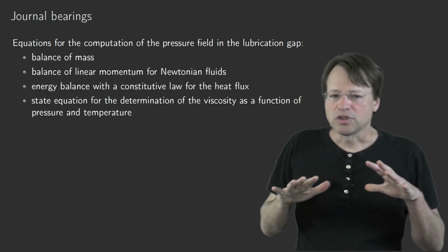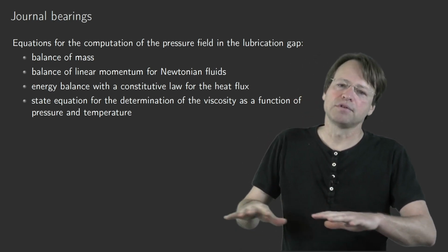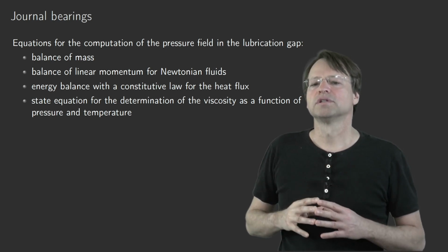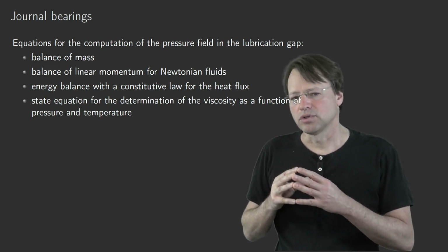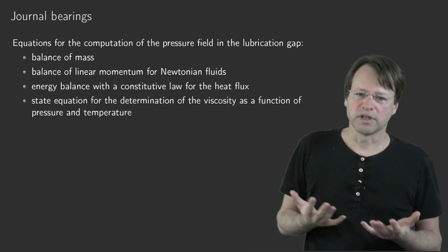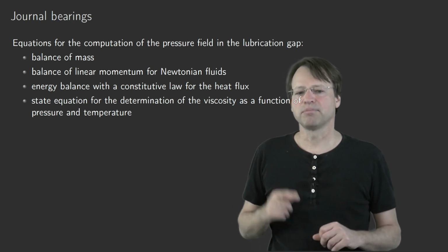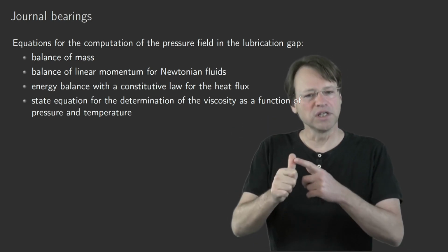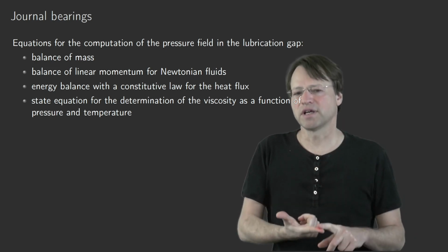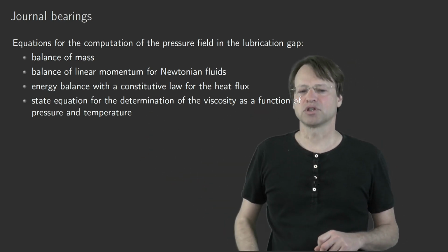And if you assume that approximately these two effects balance, so that we get a kind of average viscosity from these two effects, then you can conclude that the viscosity is approximately independent of both parameters in the convergent lubrication gap, because there's one effect that tends to increase the viscosity, namely the increase of pressure, and there is another effect that tends to decrease the viscosity, namely the increase in temperature.